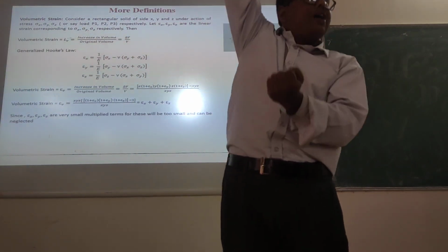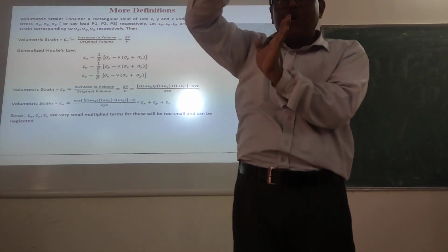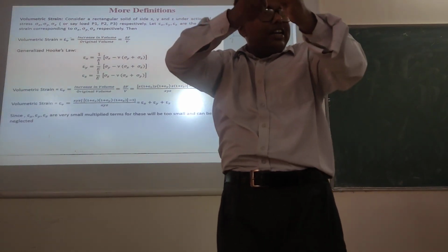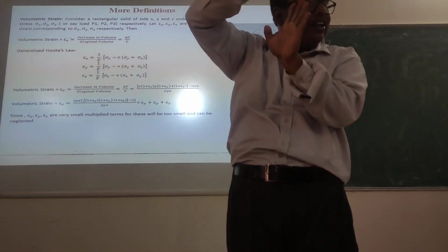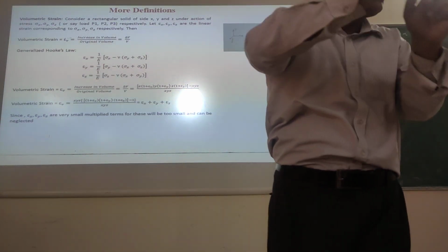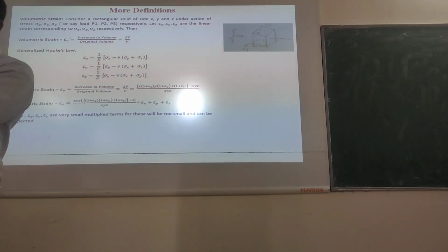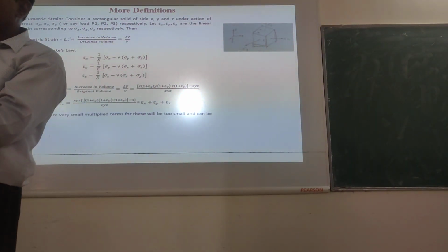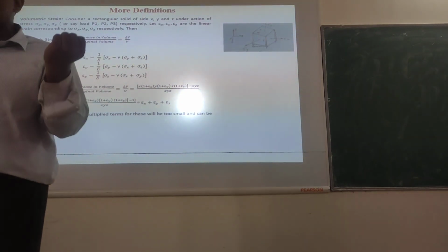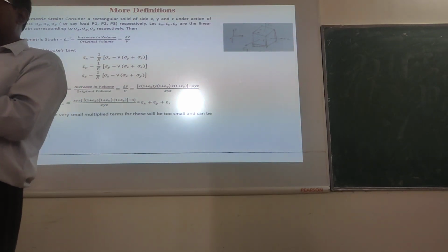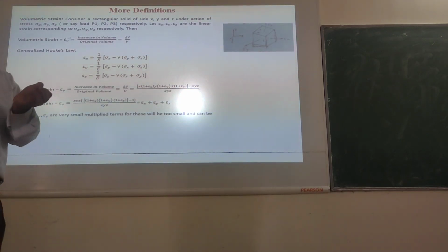In the direction where I have applied the pull, in the Z direction also there will be some compression. Will there be or not? If you understand, Poisson's ratio comes into the picture. So in the longitudinal elongation, and because of the mutually perpendicular stresses acting on the other faces of the body, there will be lateral compressions, and that's where the strain will change.